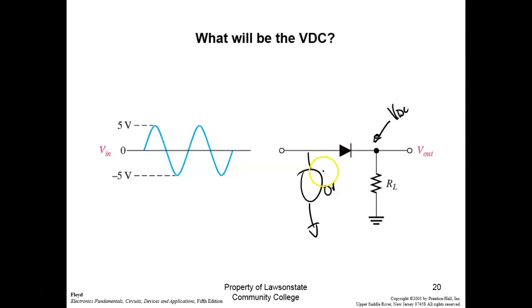So if I had my meter set on DC right here, over here it measures 0. If I take my same meter and put it over here, set to DC, it's going to measure, what'd you say, Bernard? About 1.6 volts. Now why does it measure 0 over here and 1.6 volts over here? Over here it's going to be the average of a sine wave. Over here this is DC. It's going to measure the DC work that I'm going to get out of it. So I got 1.6 volts over here somewhere.